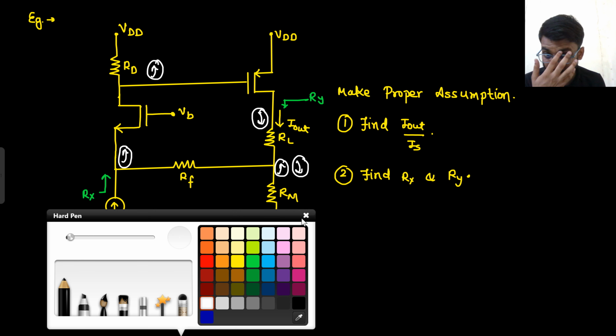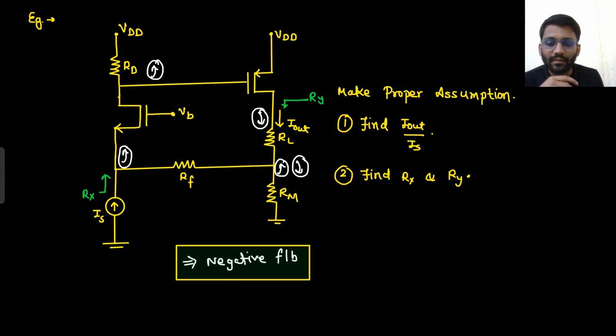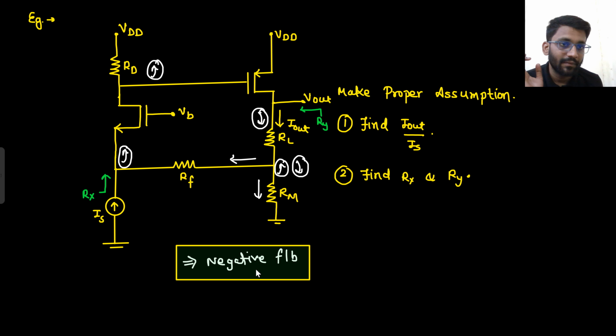Well and good. What kind of feedback topology is there? For feedback topology, let's just first put the Vout value. Vout value should have been given here. Let's just assume this is your Vout, and they should give Ry like this. This is your Ry, right? So output current, this is I out, that is coming, that is being divided into two paths. So there is current being sampled. Now current will be mixed. Let's see the mixing first. Forget about sampling. Let's see the mixing first. So this IS current has two paths, this path and this path. So certainly you can say current mixing.